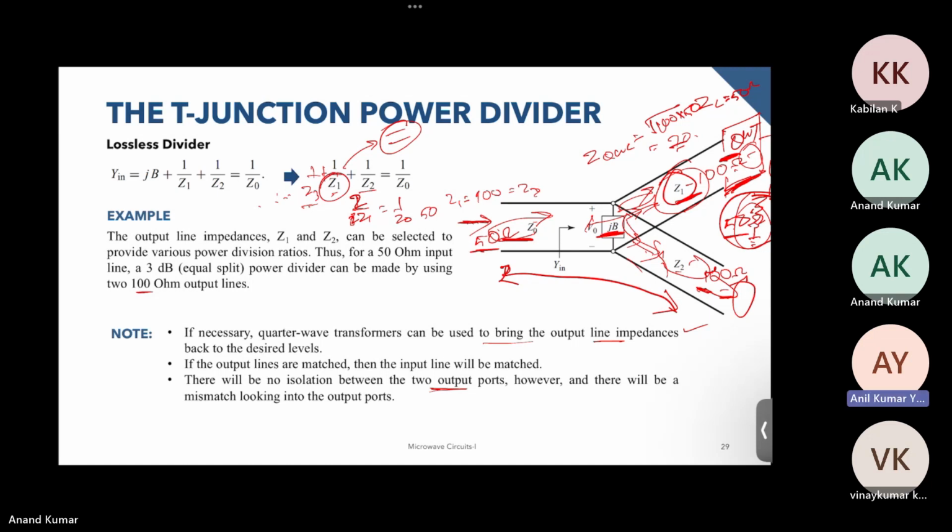And one more question: the thickness determines the impedance. Does the length affect the phase offered by that microstrip line? Yes, the length will affect the phase. So if you want all the arms to give the same phase, then you have to make sure that each of these lengths is equal.